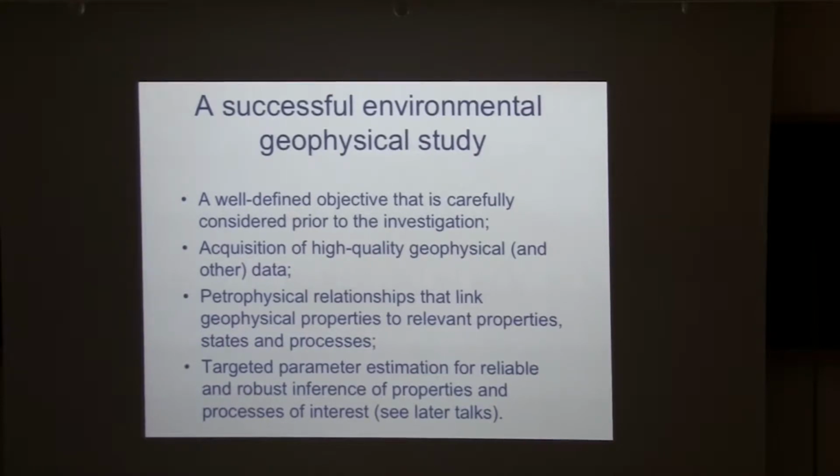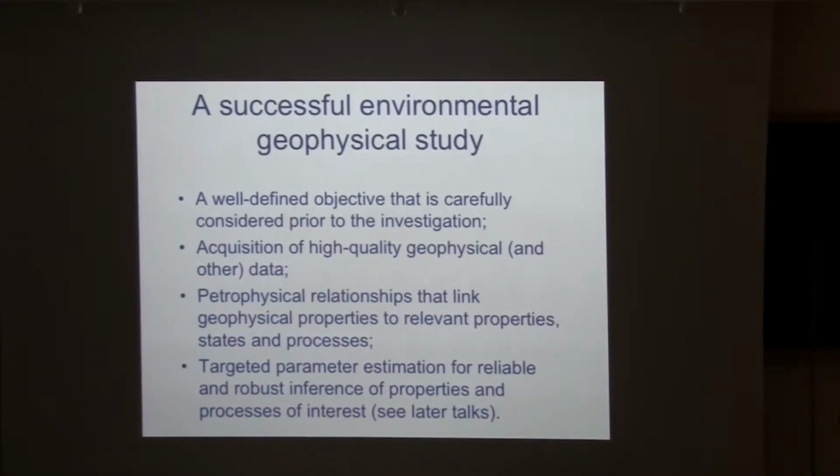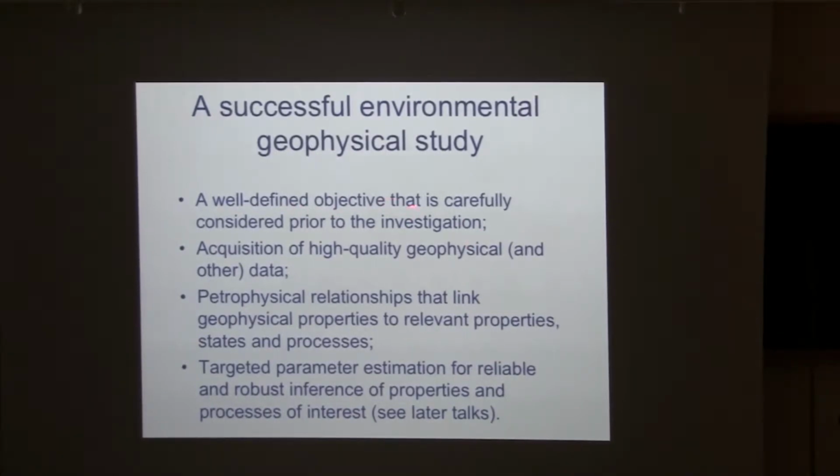Okay? So if you want to be successful, this is a little bit my recipe here, very briefly. You need to have a well-defined objective, so you need to know why you're going to use geophysics. And then you need to talk with people that know something about geophysics if you're not the expert. So you need to define a survey that allows you to actually have a chance to respond to that objective. There are many cases where people maybe want to see, I want to see a fracture at 200 meters depth. The aperture is 1 millimeter, and I'm going to do whatever, ERT to do this. It's not going to work. So consider things beforehand, do proper analysis, and you will actually be able to use it for what it's good at.